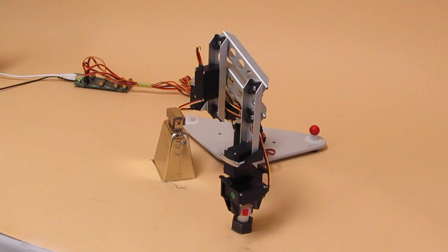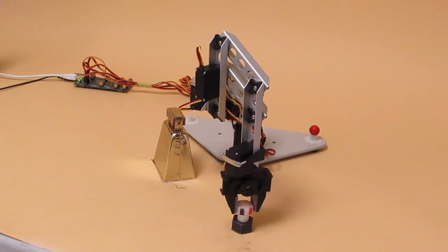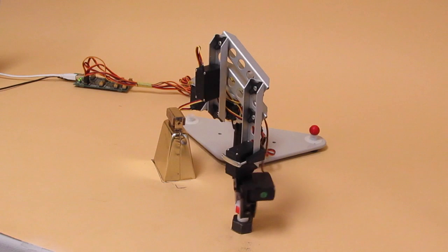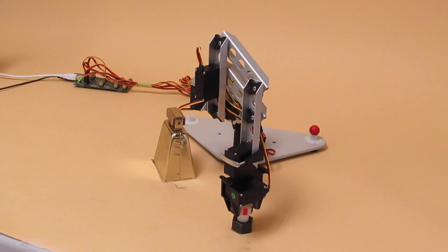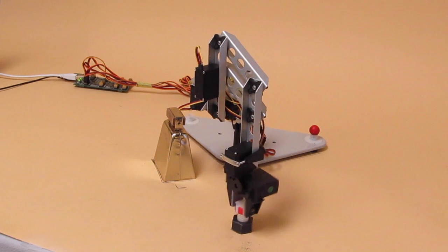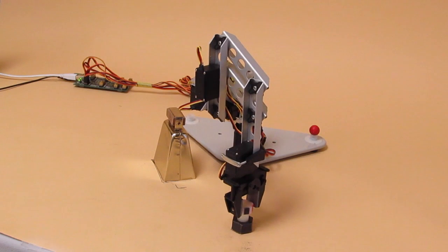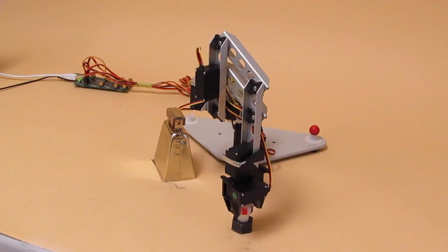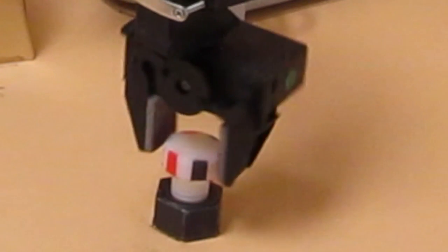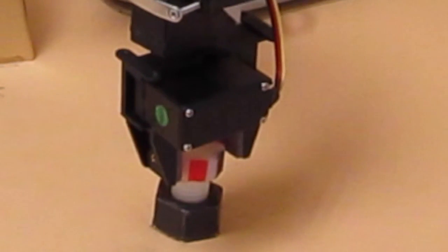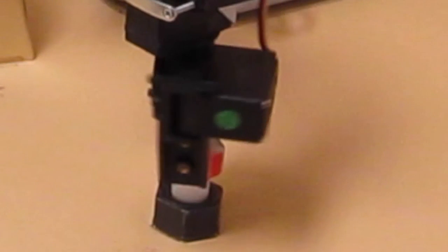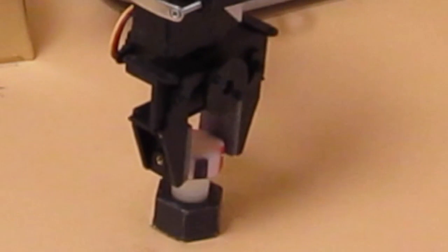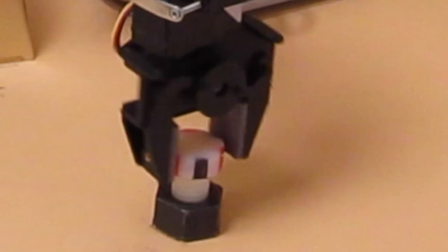Notice that the whole body of the robot shudders slightly during the turning operation. This is a result of misalignment between gripper and screw. Notice also that this same misalignment causes rubbing between one of the fingers on the gripper and the screw, producing undesired turning.